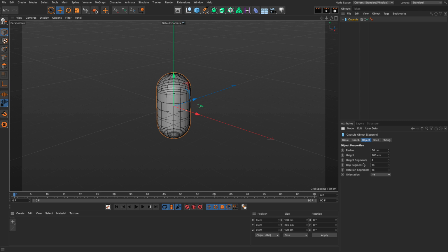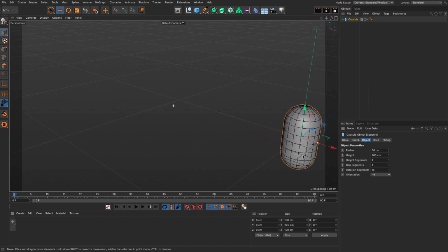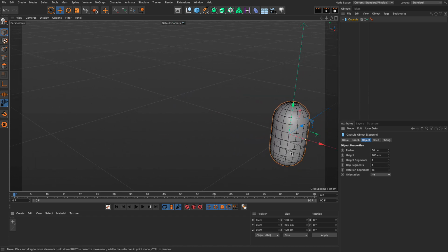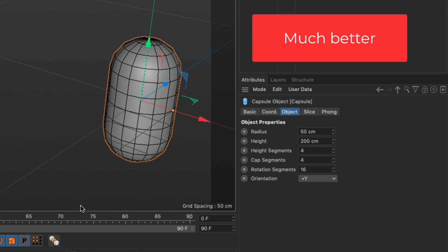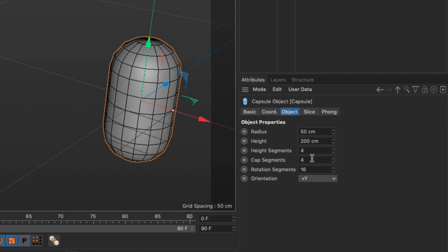Now here's a key moment, something we're going to do in the next video when we start recording this, and that is the following. If you're planning to zoom in to show the attribute manager, what you can do is navigate, bring this close to here, then zoom in this area so that it's very obvious when you change a particular parameter, for example, the cap segments to 16 and press enter, they can immediately and clearly see what changed.